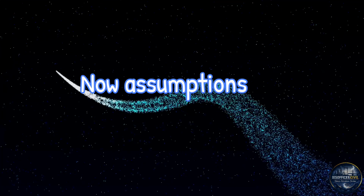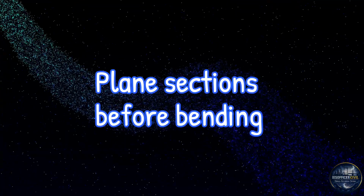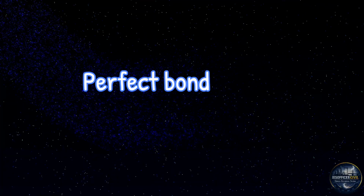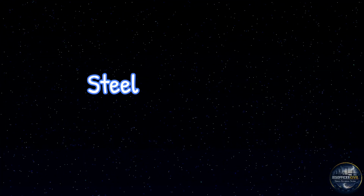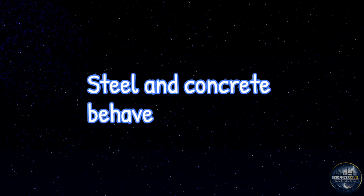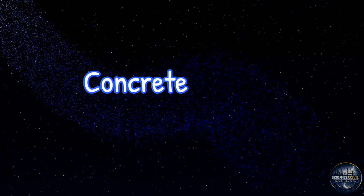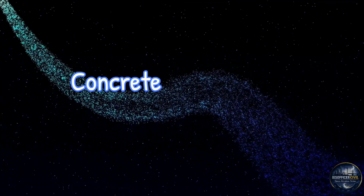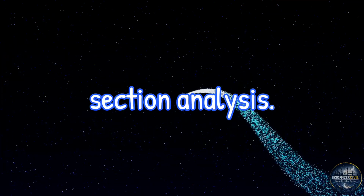Now assumptions of working stress method. Plane sections before bending remain plane after bending. Perfect bond exists between steel and concrete. Steel and concrete behave elastically within working stress range. Concrete carries compression, steel carries tension. Concrete in tension is neglected in cracked section analysis.